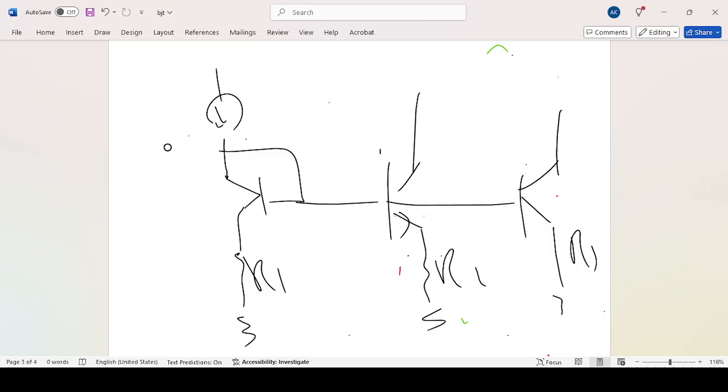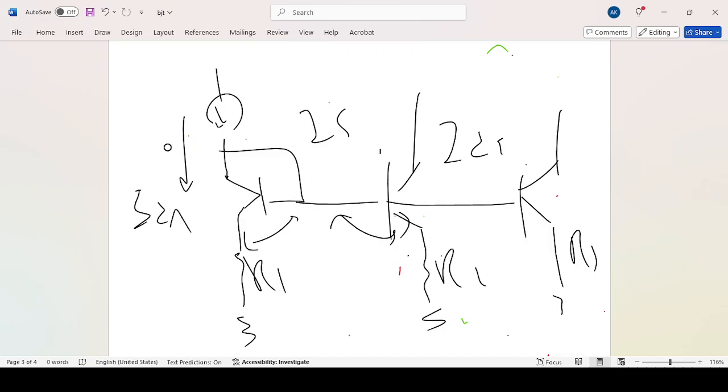You can see that, for example, the IC1, IC2 relation is dependent on the VBEs and IS of the transistors, and you can easily copy this thing without the matching considerations, but still you would have the ratio between them, and you can copy them, reduce them, without changing the sizing of the transistors, and then just the ratio R2, R3.